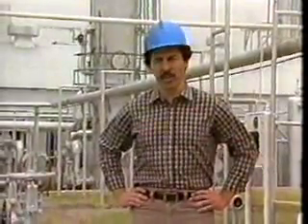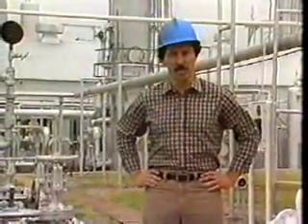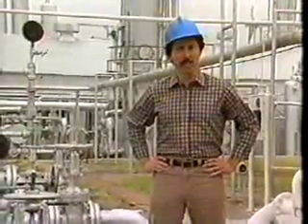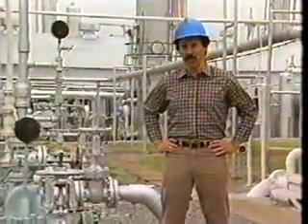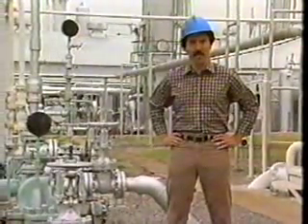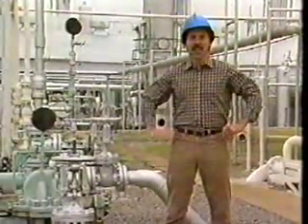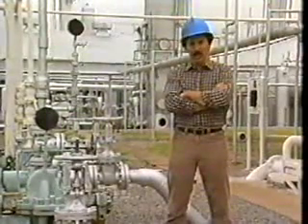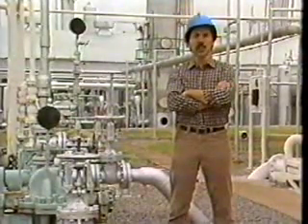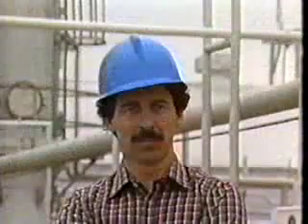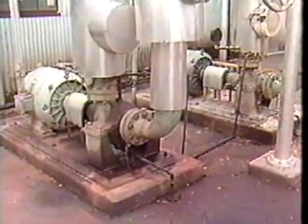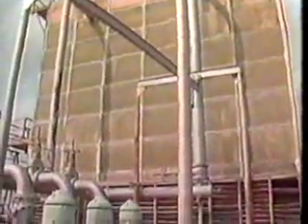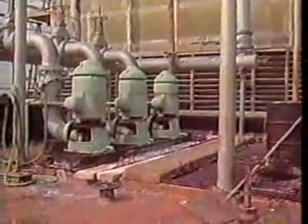Those with pistons or gears are called positive displacement pumps. And those we'll talk about today, centrifugal pumps. Another module focuses on positive displacement pumps, so we won't spend any time on those right now. So, when are centrifugal pumps used? Usually when you have to move a lot of fluid, like emptying storage tanks, moving processed fluids in gas plants, providing emergency fire water, circulating cooling tower water, and, well, many, many other applications.